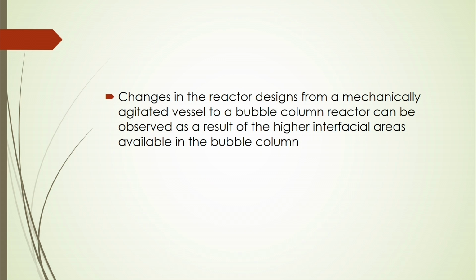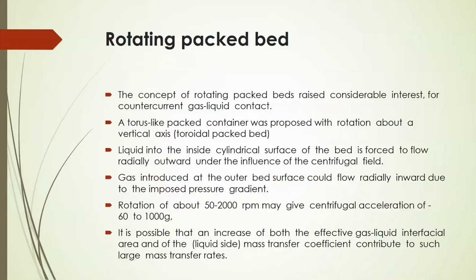So that is why you can think of the design of equipment in a novel way, to get better mass transfer just by creating more interfacial area, and also case to case, where the residence time will be required as low or high. Accordingly you can devise and design different types of column or reactor to produce that interfacial area.